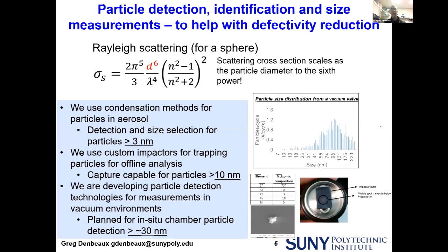We do a variety of different topic areas. Another big one right now for us is nanoparticles and nanoparticle detection. The primary focus here is for detecting nanoparticles in semiconductor processing tools, because if you have a wafer and a particle lands there, that's going to be a defect and that device might fail. If a particle lands on the mask, which then prints on the wafer over and over again, then all the devices are going to fail.